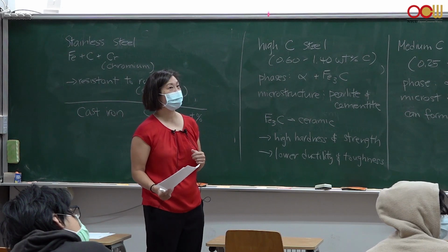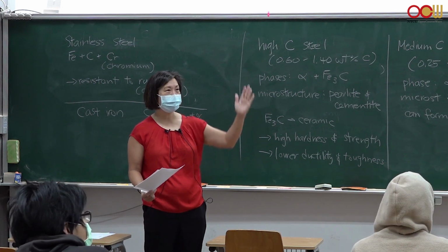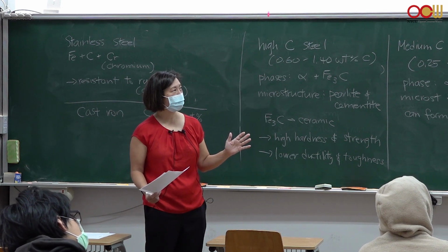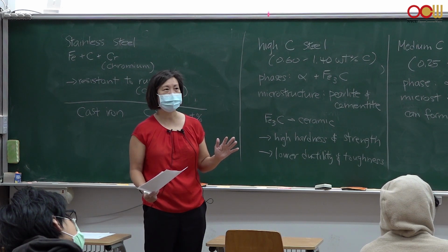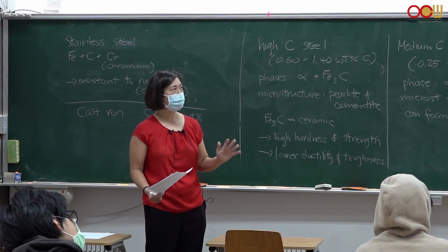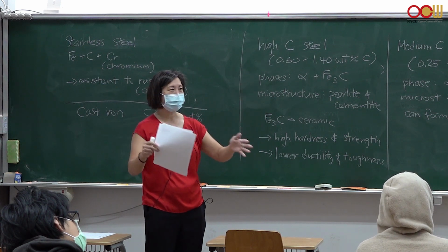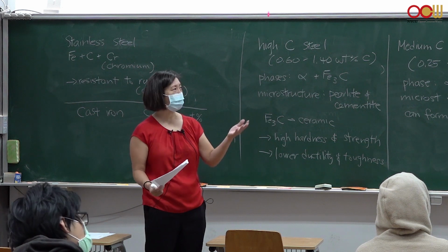Right, eutectic. That's a eutectic point where, without varying the concentration, if you just lower the temperature, it goes from liquid to two different solids, right? Without going through a liquid plus solid region. Okay, so that's a eutectic point. Eutectic points affect the microstructure. If you're under the eutectic or over the eutectic, it will change the microstructure.